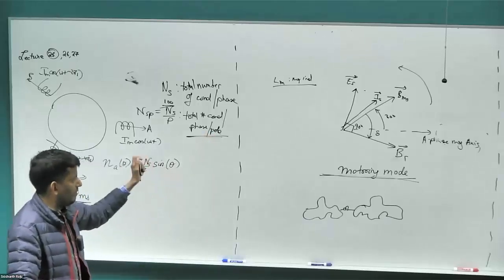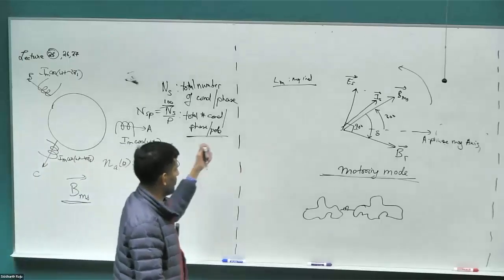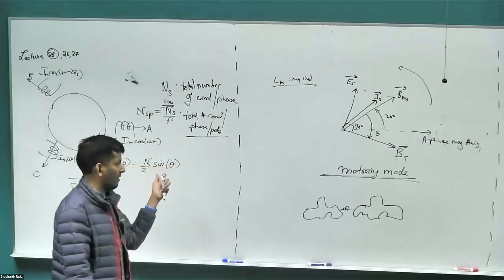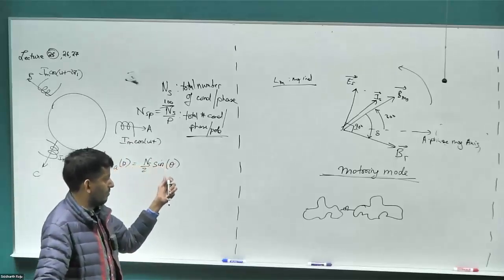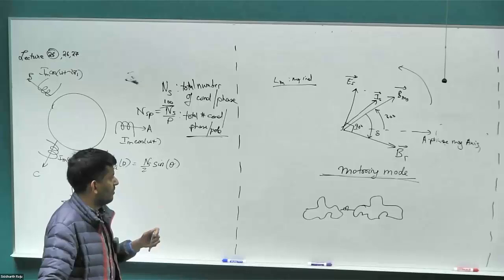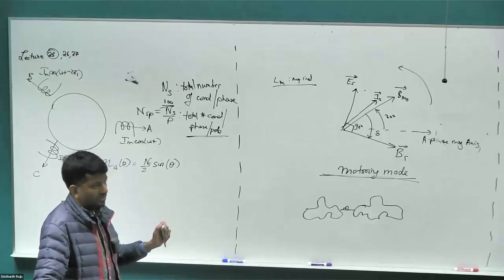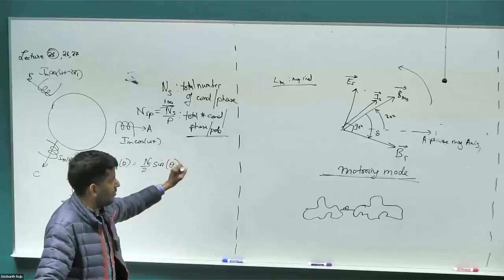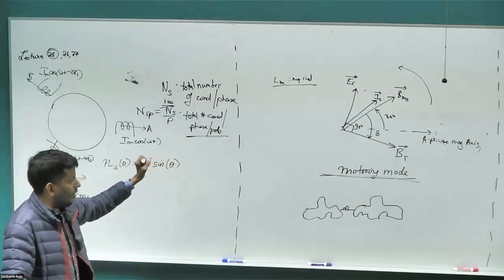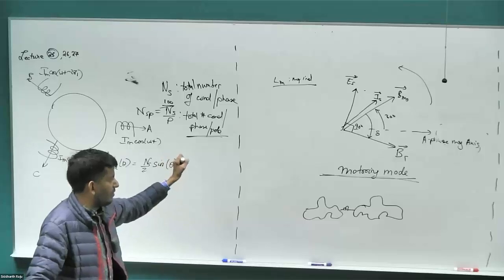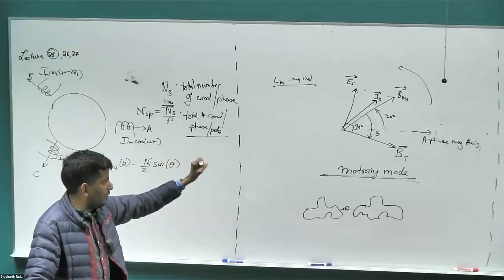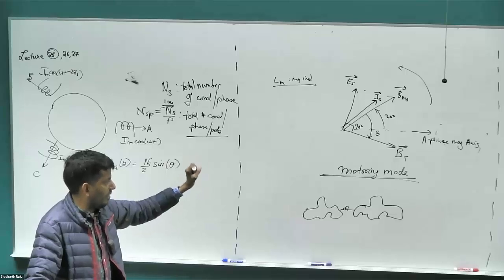All the equations that we have derived, when we go from three-phase entity to space vector entity, if we have balanced voltages, or we have a three-wire system, where currents may or may not be balanced but still the sum of the currents will be zero, then the space vector transformation doesn't lose any information going from ABC to space vector. So whatever equations we derive in the time domain will hold true for every single phase, and will hold true even for the space vector notation, as long as the transformation is linear. I'll show an example where it will fail when the transformation becomes non-linear.